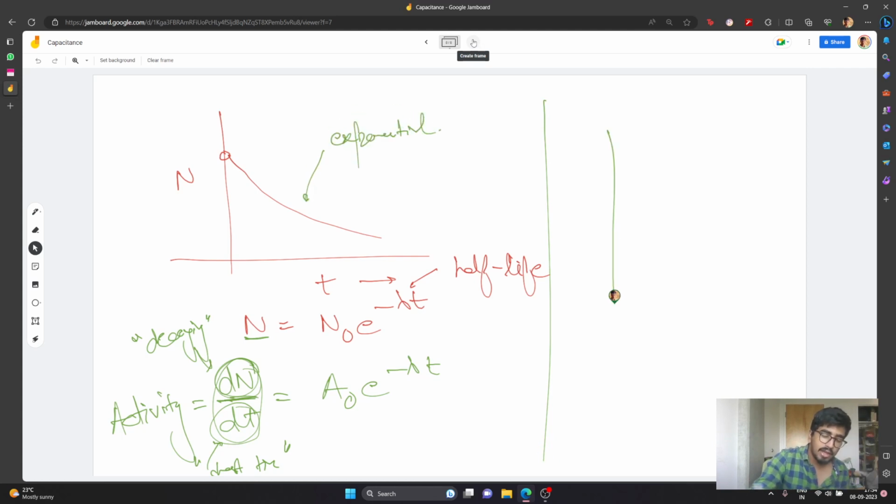And similarly here, in the case of discharging or charging of a capacitor, in charging the charge rises but the current falls, right? In the case of discharging, the capacitor is already charged, with a full capacitor. In that case, the charge itself falls, right? In the case of discharging. So just make note of my words here. Say this is a discharging circuit, and this is a charging up circuit, right? In both of these cases, the charge goes through an exponential curve. In one case, it falls through an exponential.